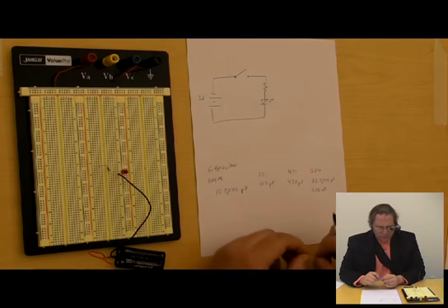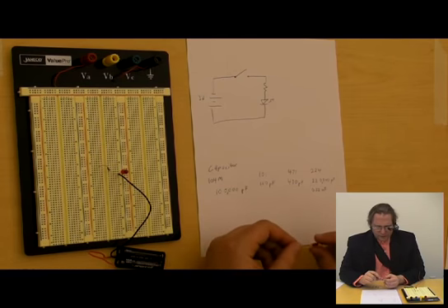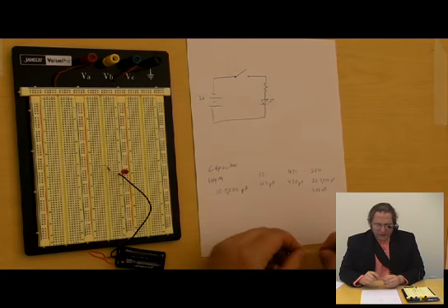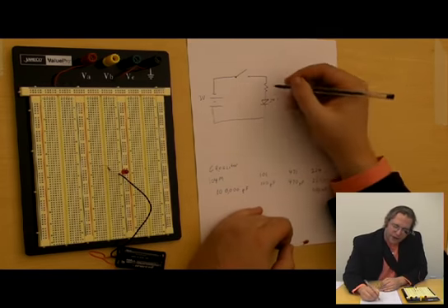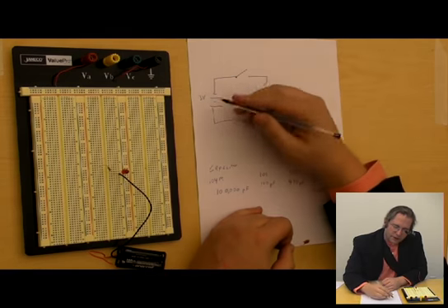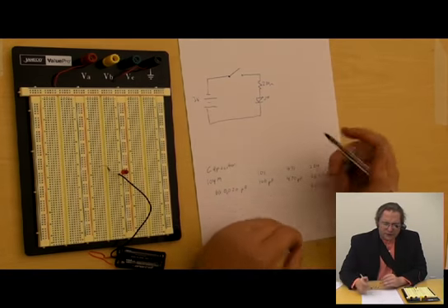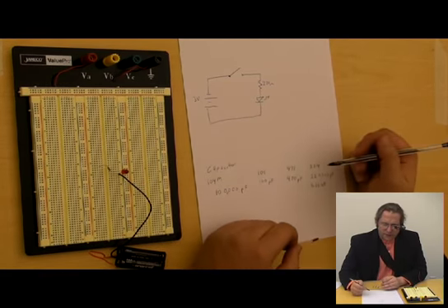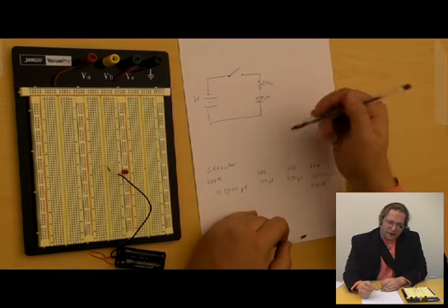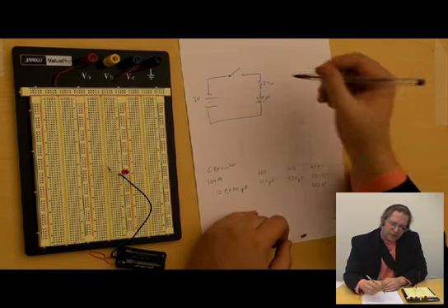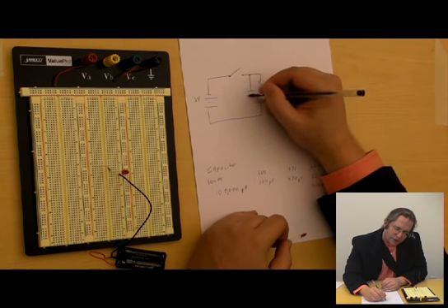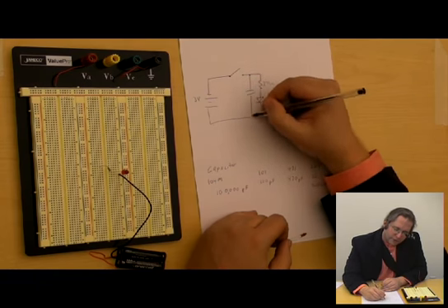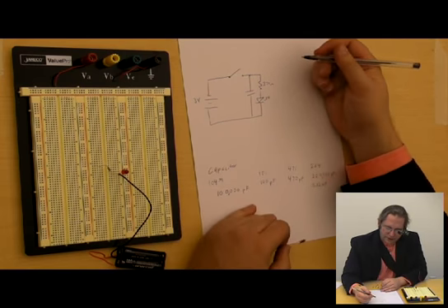Now, if I want to put a capacitor into my circuit diagram, see, before I had this as 270 ohms and a switch and 3 volts. Let me put this into the circuit diagram just across the LED. So what I'm going to do, I'm going to put it in parallel here, and I draw it as 2 plates, and draw it down.